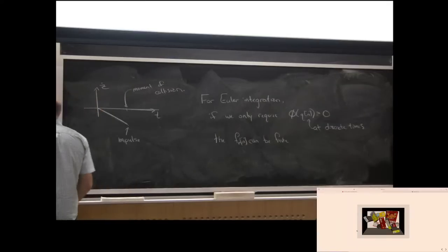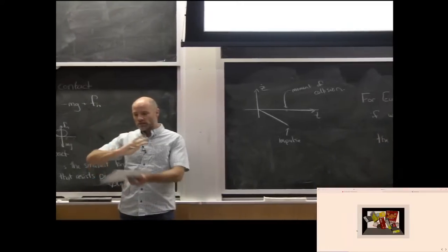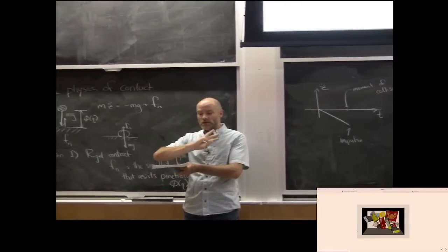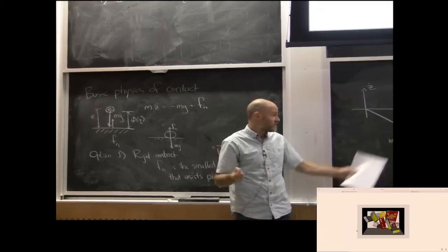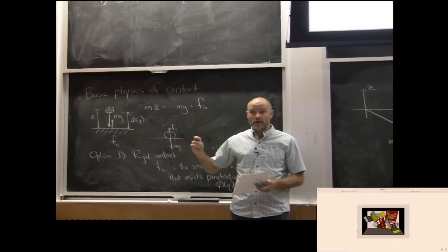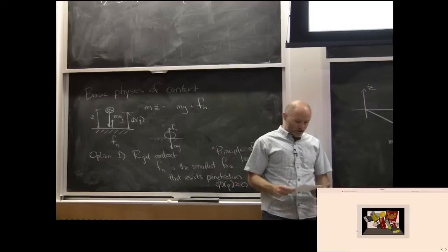Okay, but this notion of rigid-on-rigid contact, which most of our mechanics is rigid body mechanics, leads to this seeming problem where I need instantaneous forces at collision, which makes it hard to simulate accurately. If you want to simulate as accurately as possible in continuous time, you actually have to do event detection, and you have to handle that collision event explicitly, and then continue integrating. If you make a discrete time approximation, then we're going to play different tricks.